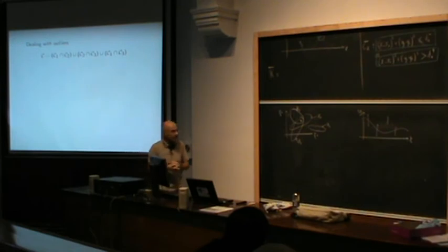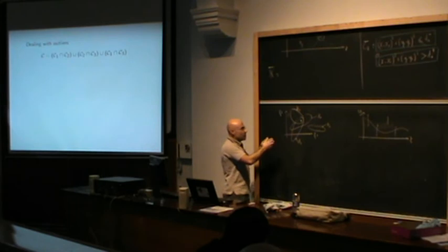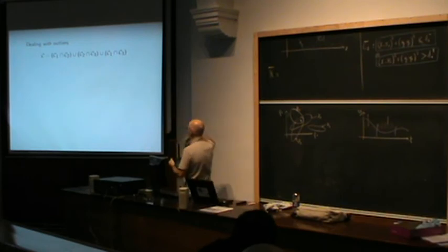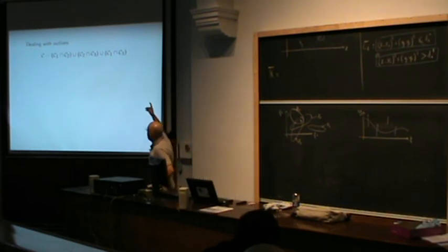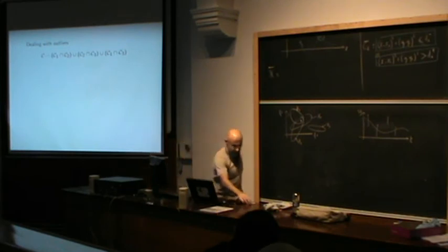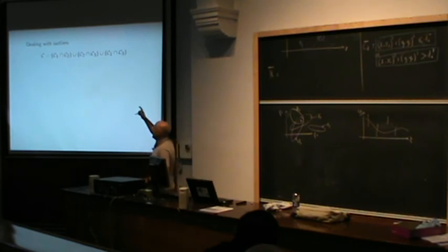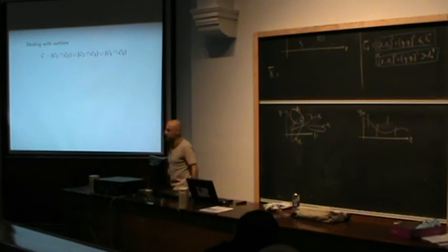So most of the time, when you have a robot, you have outliers. So if I have 3 measurements and I want to be robust with respect to 1 outlier, it means that I will build the contractor which is given by this expression.